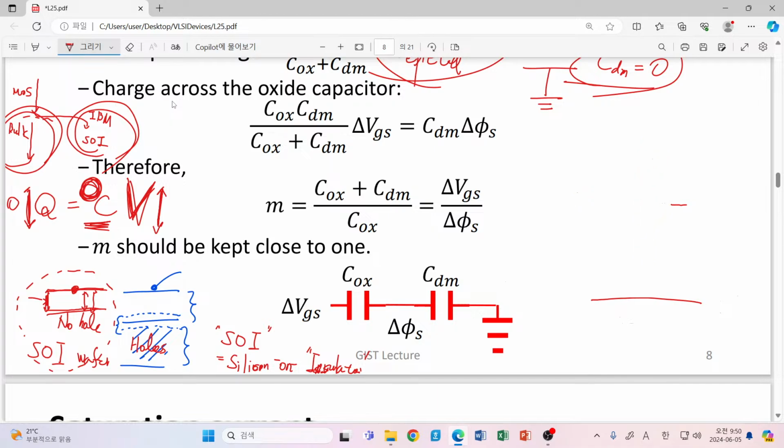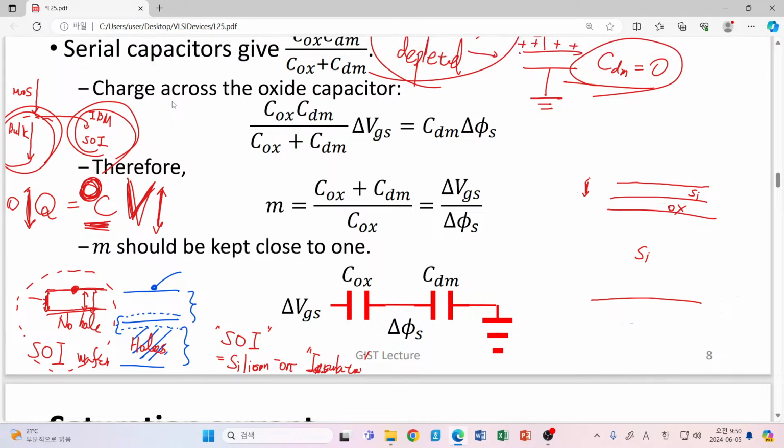Instead of silicon and oxide and a very thin silicon layer, that is the conventional SOI device, SOI wafer, and you can control the thickness. You can just place an order to your wafer company, please give me a 20 nanometer thick one or a 10 nanometer thick one, so they can make it. However, that is quite expensive. Instead of that, they made it this way.